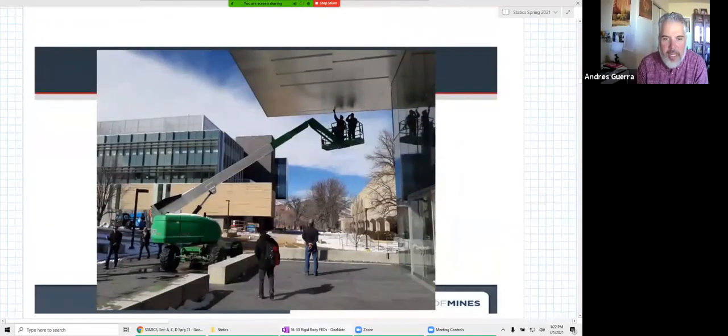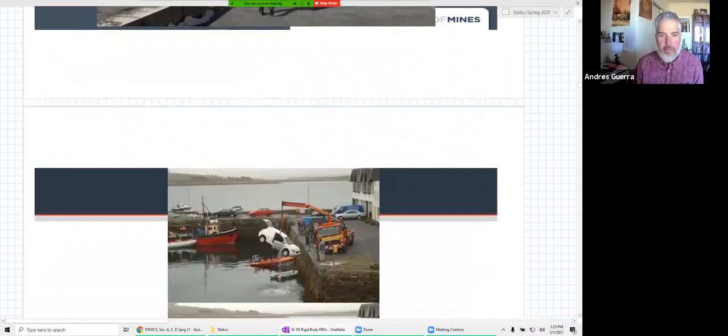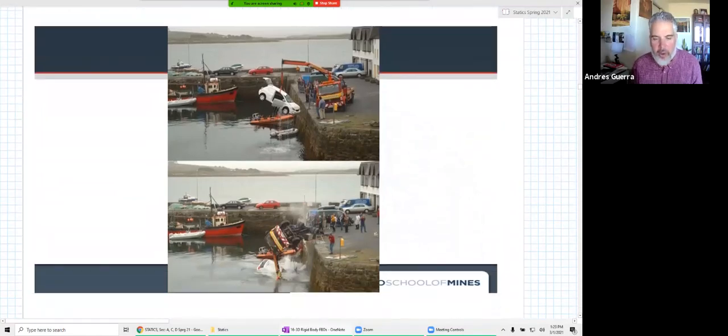Or what about this one right here in front of Marcus? Remember the cantilever example we did last time, this cantilever sticking out over Marcus. They were doing some work on the panels underneath there, and they have these people out here. Don't you think this could overturn that way and fall and go crashing through all this glass here? That would be really bad. Actually, a lot of this machinery has warning sensors that start beeping and prevent you from getting to that point where you have overturning, like that crane we looked at in this overturning stuff.